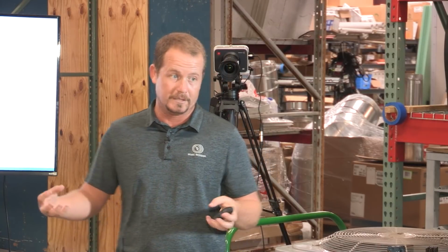And in fact, our overloads are even more than that, like we mentioned, because not only do they protect for an overcurrent condition, they protect for an overheat condition as well. Now, you do have motors, and you'll see them in commercial all the time, where those motors do not have an internal overload. They're just relying on the overload built into the starter, and that's the only overload. So you will see that. Or even in small appliances, you may have an external overload that's mounted on your compressor terminals. But there's still going to be some form of overload. There's going to be some method for independently protecting that device and the conductor that feeds it.